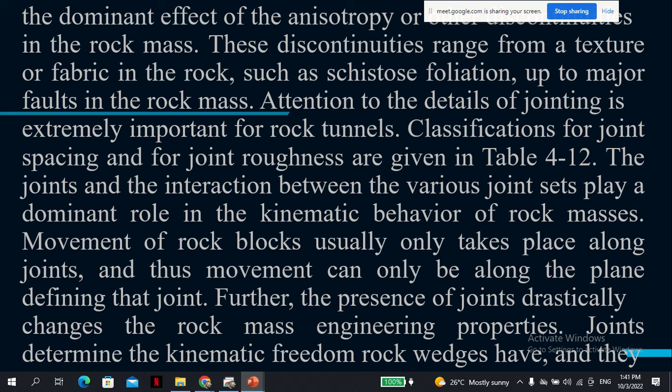We are going to decide, for example, that this rock has a rating of 41, or 50 something, or 60 or 80. How we decide this is we check how intact the rock is. We check the strength, the uniaxial compressive strength. If it is between 0 and 2 MPa, that is very weak rock. And if it is between 2 and 8 or 2 and 10, 10 and 30 and something like this, over 50, 50 to 100, the same, in fact the same classification that I've shown you before.